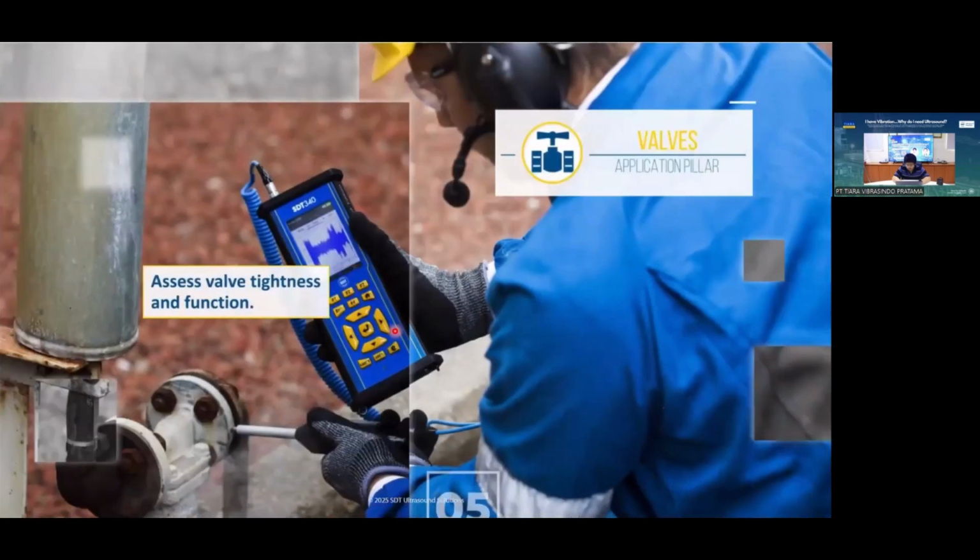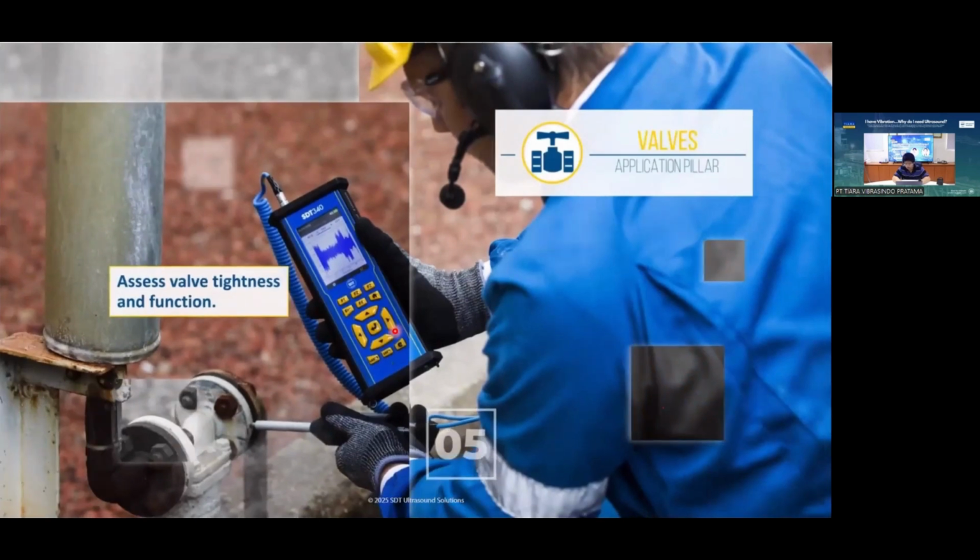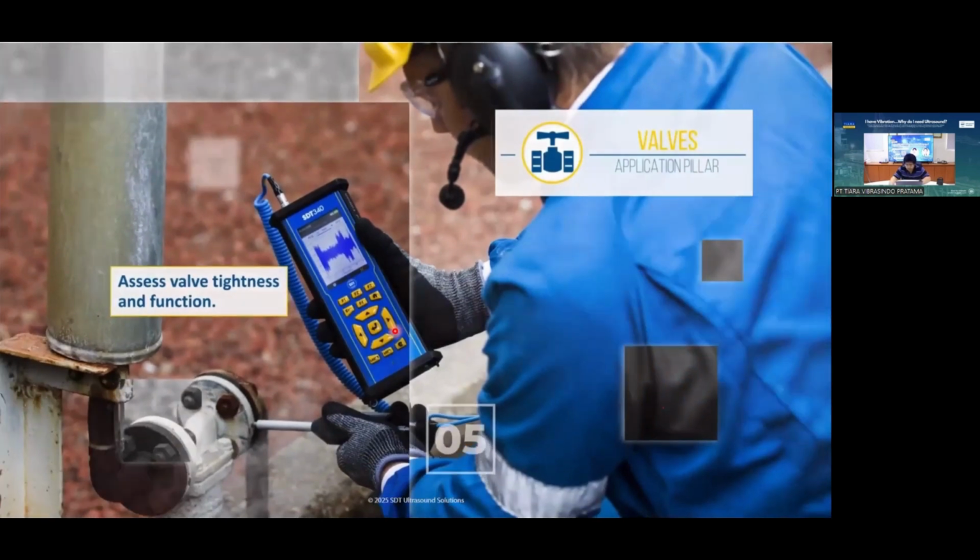Also, we have the valve application. You can assess the valve tightness and function. I think every manufacturer has maybe 1,000 or 2,000 valves, but how do you know they work properly or not? Do they leak or not? You can use the ultrasound device with the sensor to measure the sound when you close the valve, because in a process valve, if it leaks, it affects production also.